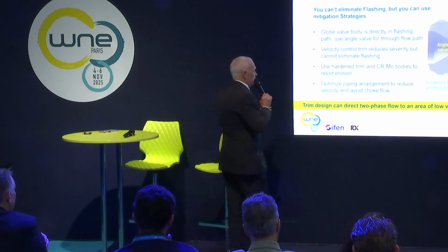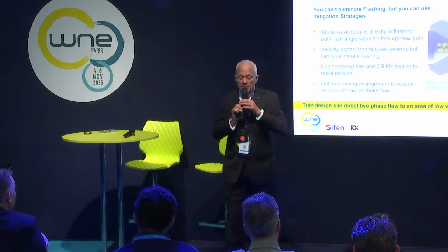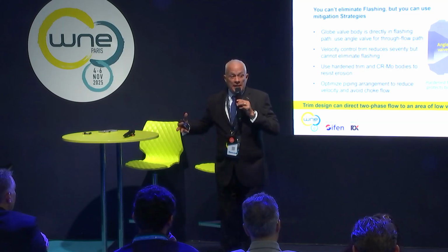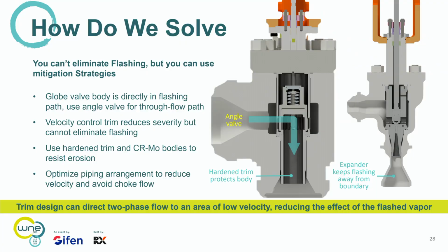So the other thing, when you're turning from this liquid to the two-phase flow, remember, as a liquid turns into the gas, it's expanding. Okay, where's it going? Where's that expansion going? If you don't have a larger outlet on the valve, then basically you're choking the flow. When you start choking the flow, you have a problem controlling that whole system because it's just clogged up there.